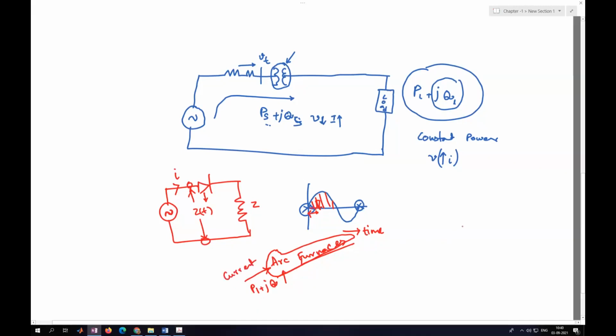Even in the olden days, when we didn't have the apartment culture, every individual house had an induction motor to pump the water. Whenever we switched on the motor, the illumination would show a dip. That means the induction motor during starting takes a high magnetizing current.